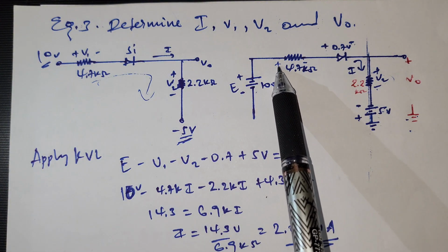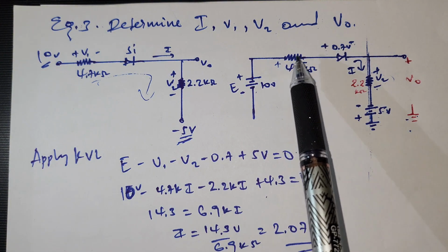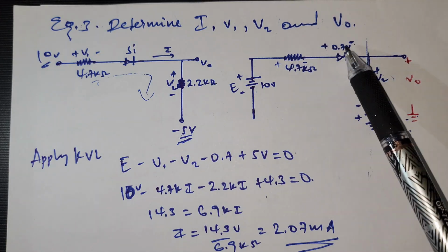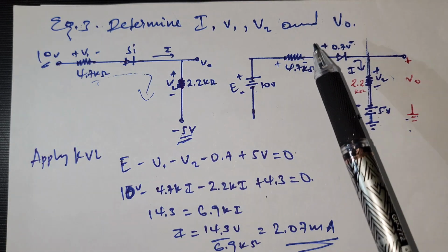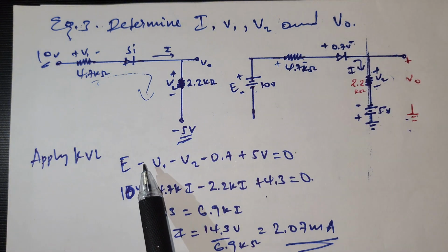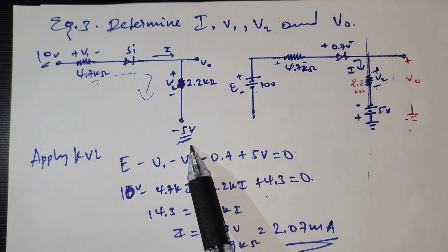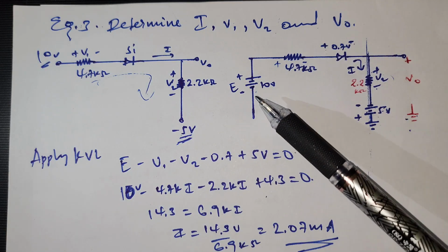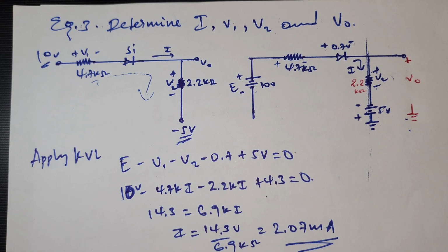You see this positive terminal to negative, and positive terminal to negative. These two are the same. Also these three components are negative. We set them negative because they consume voltage. These two are the sources. These two deliver voltage. These three components consume voltage.